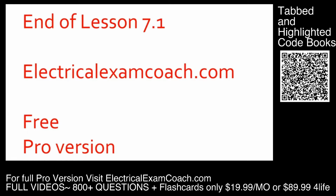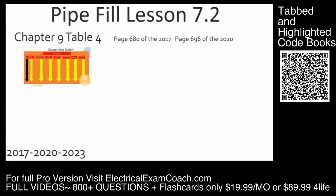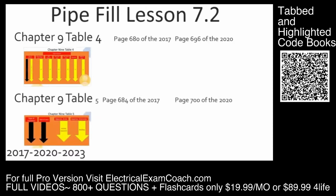Let's get to it. Hey everyone, welcome back. I am the Electrical Code Coach, and we're picking right up in pipe fill. This is lesson 7.2. In our previous video, we learned that if the conductors are all of the same size and insulation type, we can just head straight to Annex C to answer all of our pipe fill questions. But when they're not, we're going to learn what to do today. We're going to learn about Chapter 9, Table 4 and Chapter 9, Table 5.